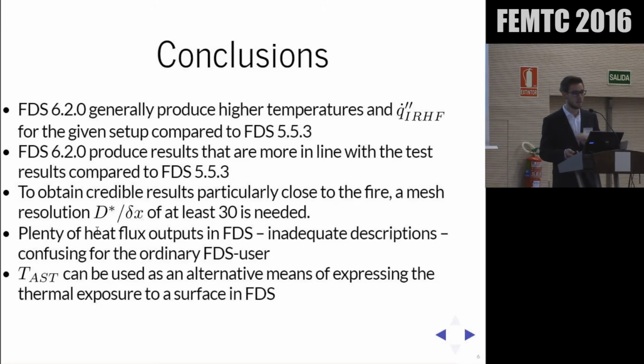For example, regarding the term incident heat flux, when I read that term, I refer to a flux that is coming into a surface, not yet penetrating the surface. And the incident heat flux should then only include the gross heat flux terms.